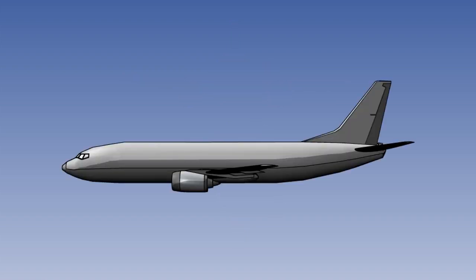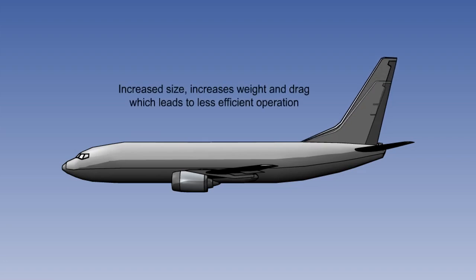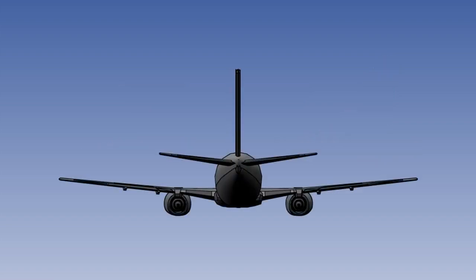Having just learnt about Dutch roll, we will now need to look at a way of countering its effects to make flying a little more comfortable for the crew and passengers alike. There are numerous things we could design to try and counter Dutch roll, like increasing the size of the fin, but the negative effects of these changes outweigh their benefits. So what is needed is a self-contained inner-loop stabilization system, like an autopilot inner loop, which is independent of the autopilot and is known as a yaw damper.